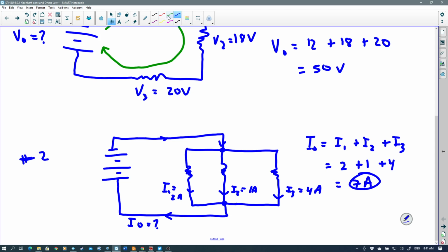Now, before I move on to the next example, the voltage law still works here, but there are multiple circuits. So if we knew the voltage going through this battery, let's say it was 12 volts, through a circuit. Well, how could I draw the circuits here? Well, my first circuit I could draw going through this branch. It's not quite a circle in this case, but it is a circuit. That's the path that the electrons would take. The voltage that you gain in the battery has to be lost in the resistor. Well, if you gain 12 volts, you got to lose 12 volts in this scenario.